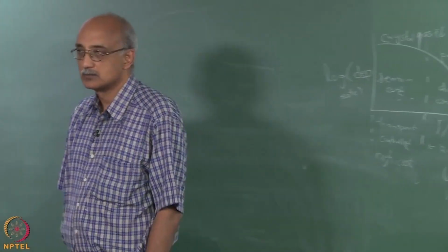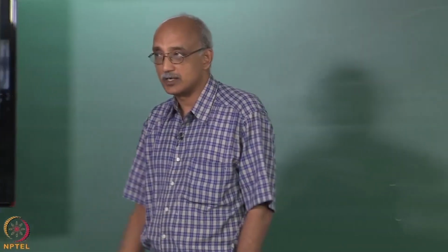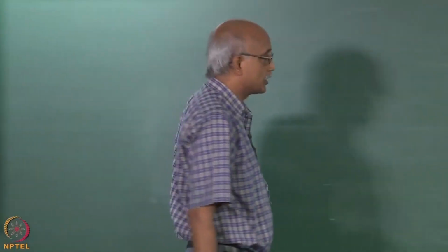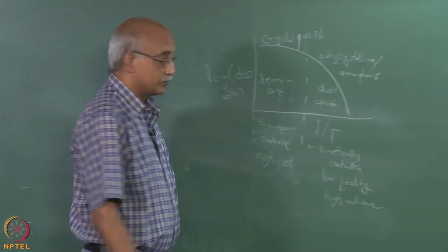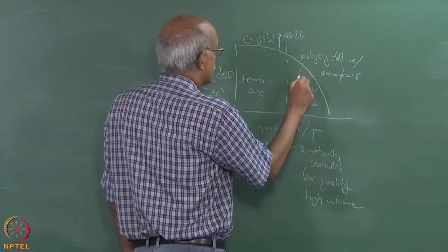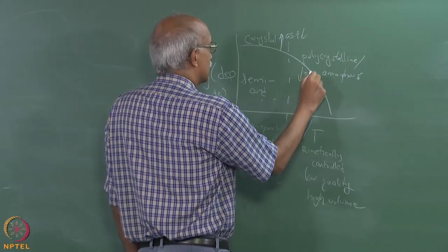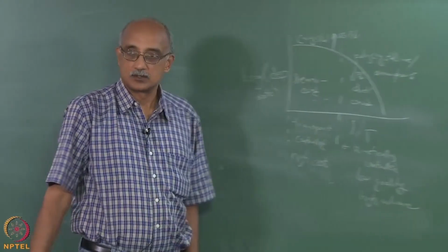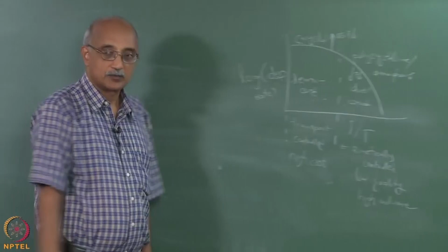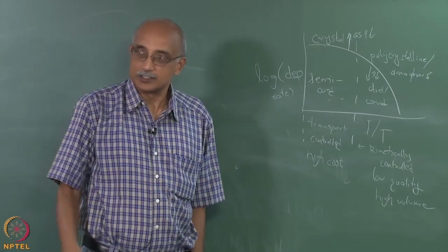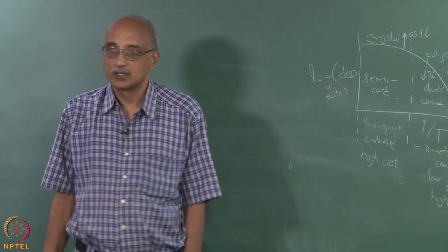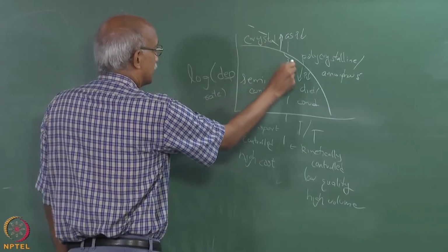A lower pressure would make the kinetics run even slower, right. So, it will have the reverse effect. The process will slow down, and the film may not even form if your pressure is too low. So, here the deposition rate decreases as pressure decreases. So, overall, if I want to sketch the effect of pressure on this curve, and this may be one of your questions in the quiz, you have to know these qualitative dependencies, right. So, it may look something like this.